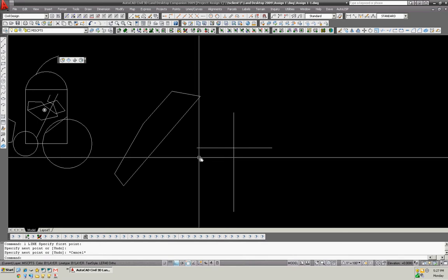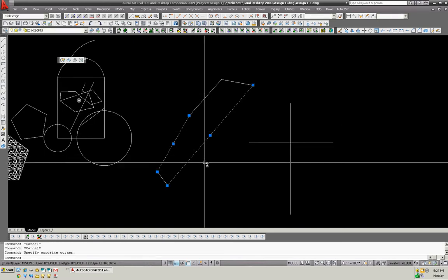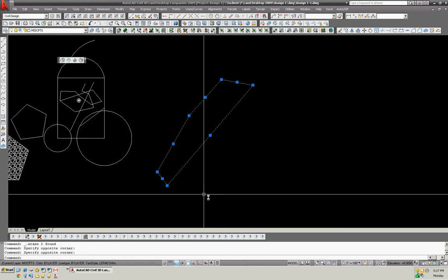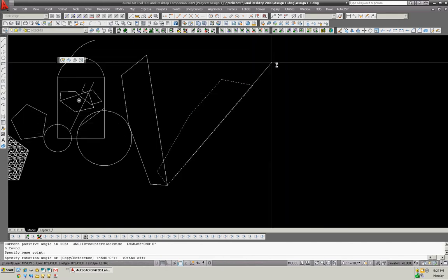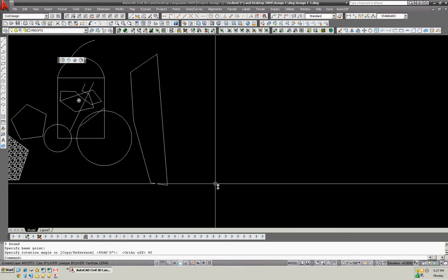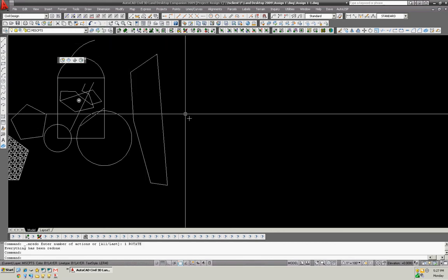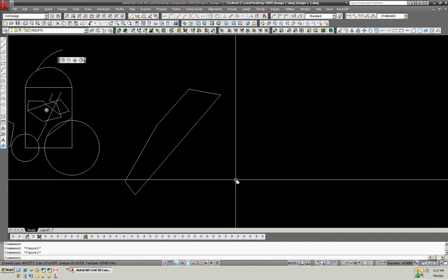If you ever rotate the wrong way, type in undo, and it'll undo that command. So as an example, let's say I'm going to delete this now. I'm going to rotate. Let's say that I rotated this 45 degrees again, and that was incorrect. I would hit either undo or Control Z. Control Z is a quick command for undo. So that's how to rotate.